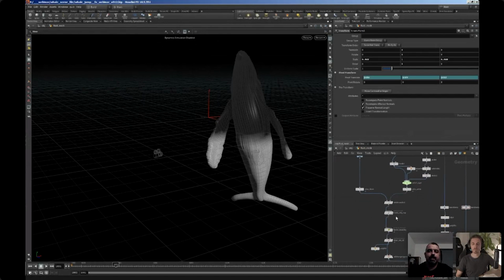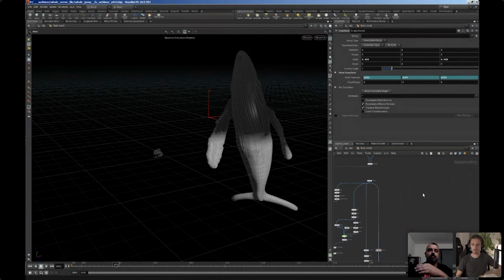It's the meshing stage, and you have complete control over where and how you want to blend. Sometimes with a particle fluid surface, when you do the flatten and you extend, it's broken, because the flatten part is not well done, and then the extrude goes crazy.